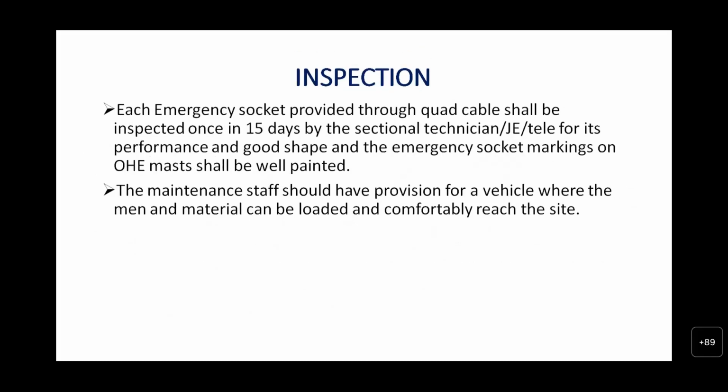Each emergency socket provided through quad cable shall be inspected once in every 15 days by a sectional technician, JE, tele for its performance and good shape, and the emergency socket marking on the OHE mast shall be well painted. The maintenance staff should have a provision for a vehicle where the men and material can be loaded and comfortably reach the site for early restoration.